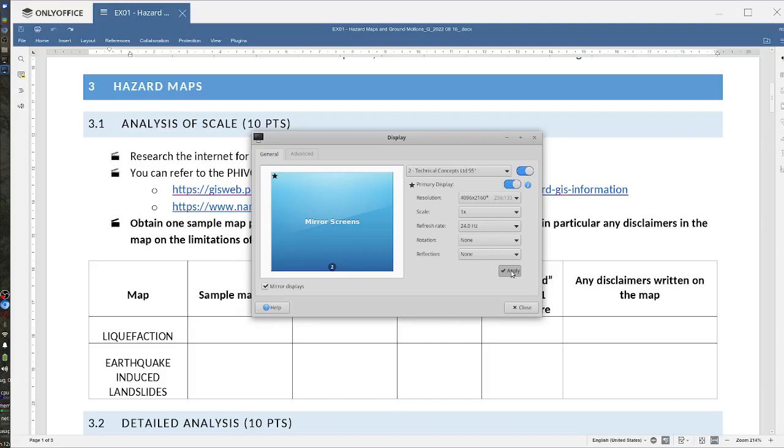And if the site is not on bedrock, you have to apply correction factors. In this case, the site is on a soft soil, so you have to multiply it by a correction factor. Okay? Soft soil, you have a correction factor of 1.39.